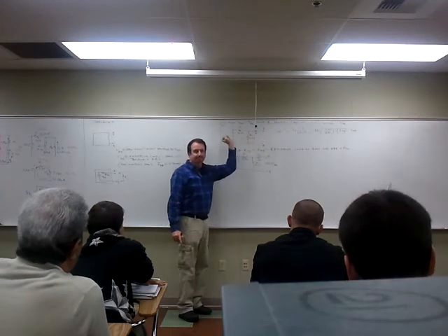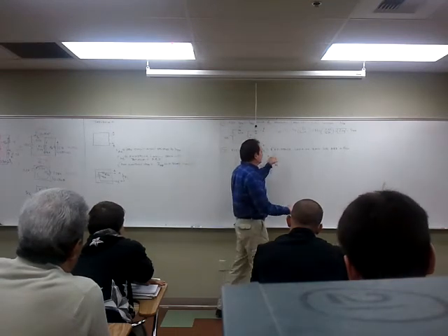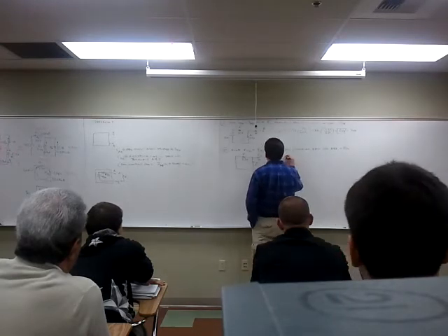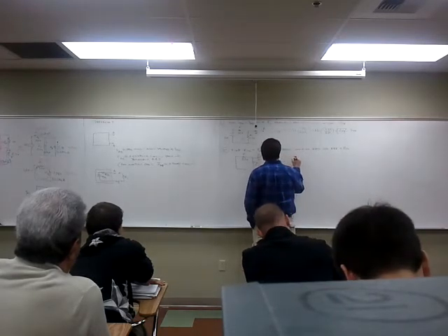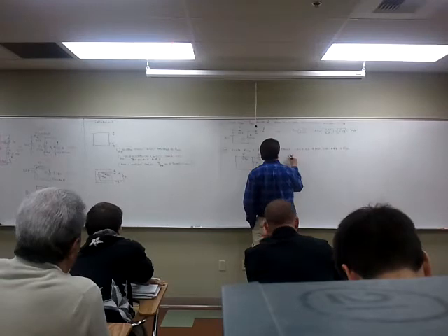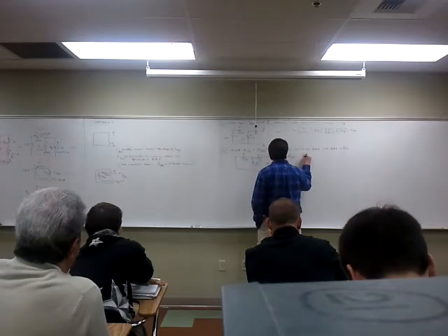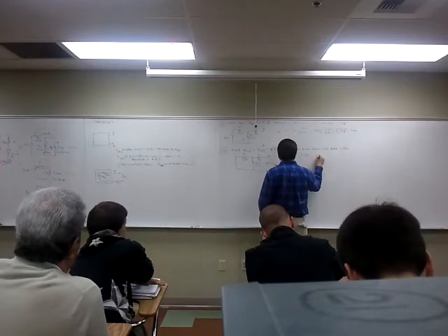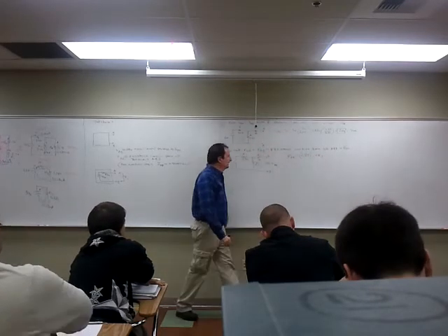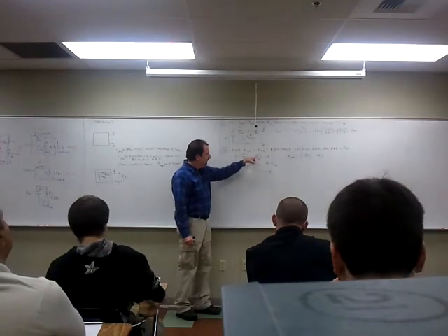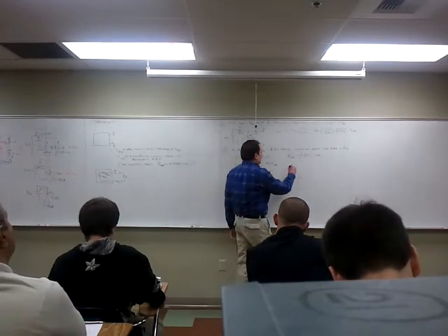Okay? So our Thevenin is the resistance looking back into A and B terminals. So what I would show here is that our Thevenin is the resistance from A to B. I'll actually write it first. So the resistance from A to B is R1 in parallel with R2, I'll just put parentheses around it, plus R3. If I did it in one step, it would be R1 in parallel with R2, plus R3.